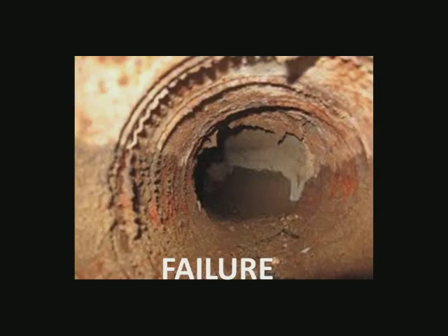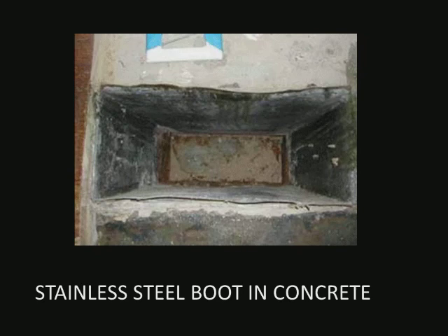Here we have the inside of the duct, which is something that a customer may never see. But if you've buried it underground and encased it in concrete, sooner or later, something of this effect is going to happen. Even a stainless steel boot encased in concrete, through freeze-thaw and acidic soil conditions, sooner or later the concrete will crack and moisture and contaminants will be able to get into the ductwork and eat away at it.